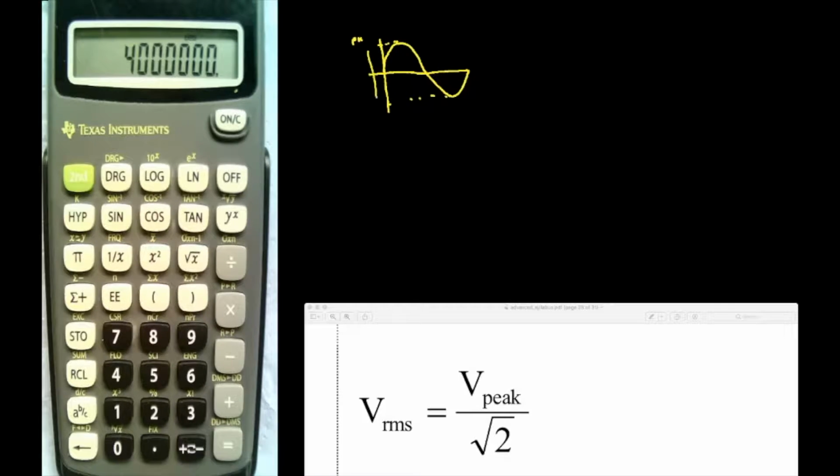That is the peak to peak. And RMS is 0.7071 times the peak. Now the RMS value, if you recall, provides the same heating effect in a simple circuit, in a resistor for example, as if it was a DC value of the same value.